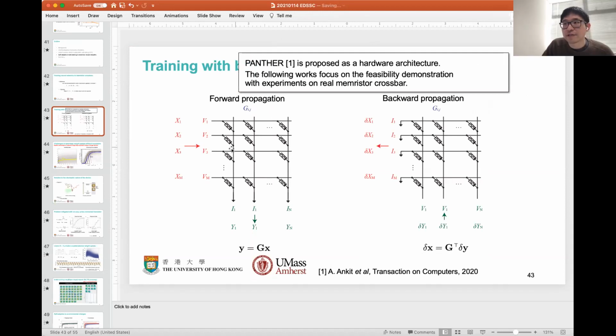But I think the key point of this training process is not to accelerate the training, because we can see a lot of challenges, as you mentioned, that many steps are not implemented in the hardware. The key point of the training is to adapt to the defects in this analog computing. So the application scenario is still inference. I think the more realistic scenario is to make the last layer trainable, with additional hardware overhead. In that case, we have to do some training directly inside this crossbar.